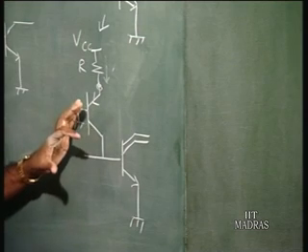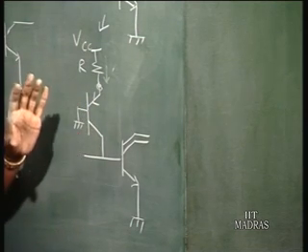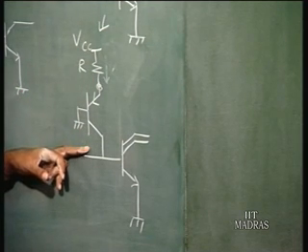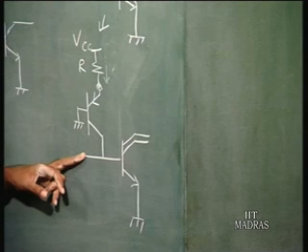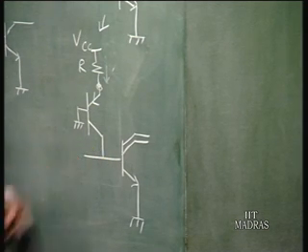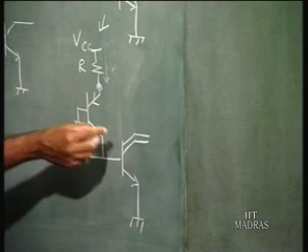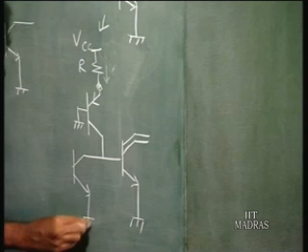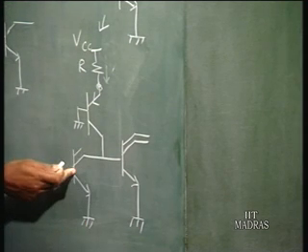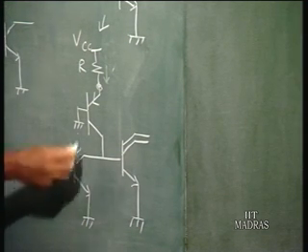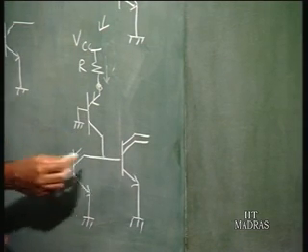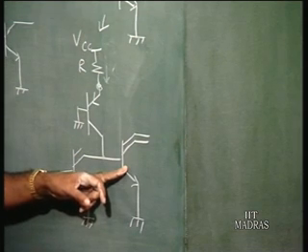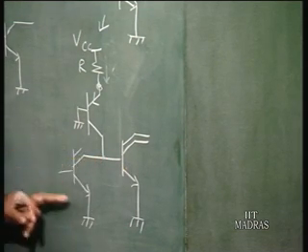Now, the way it works is again just similar to a DCTL, that is you have a current source. Now, if the input is low, what is going to happen? Basically you have another of this connected cell connected here. So, you may have another of this connected here, output point. So, if this point is low, which means that the next transistor is going to be off, not connected. And how is this low? Because this transistor is in saturation.